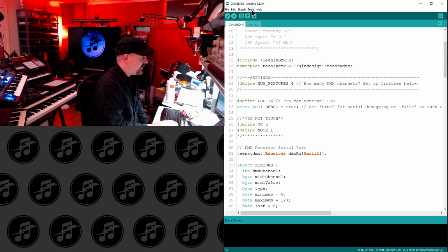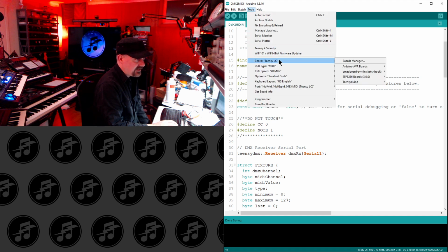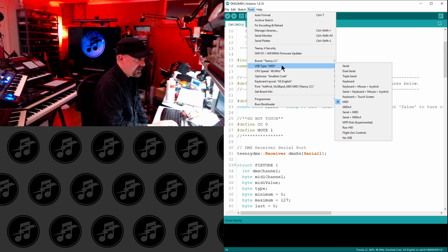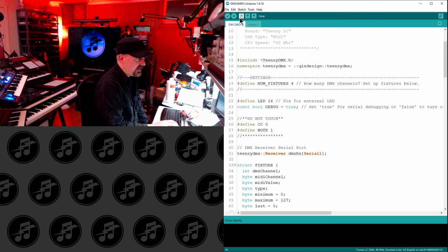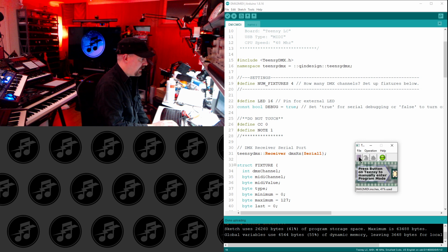So now all that's left to do is upload the program. Once again, tools, make sure your Teensy LC, type Midi, and that your Teensy is recognized and checked. And then once you've done that, just hit upload. And once it's finished, your Teensy uploader program should pop up, and you should see done uploading in the bottom here.